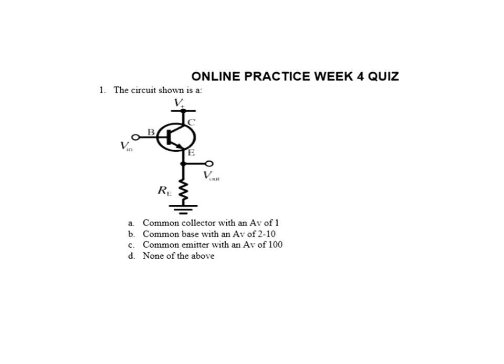Oh my. What is this circuit? What's the dead giveaway here? The collector is tied to the power supply. There's no collector resistor. The input is on the base, and the output is off of the emitter. So what is common here? What kind of common circuit configuration is this? Well, this would be common collector. So the answer for this one would be common collector. What is the voltage gain of a common collector? A voltage gain of 1 or less. Okay.